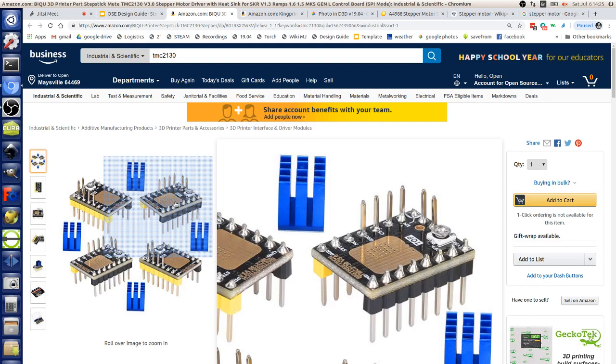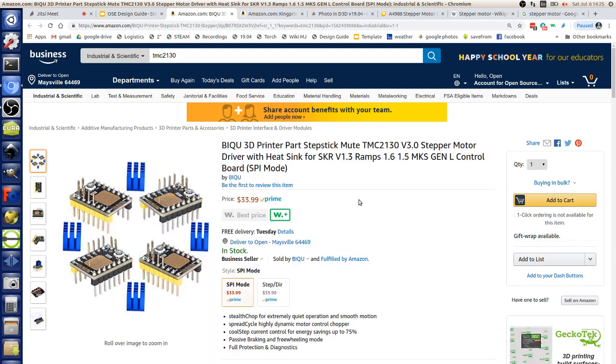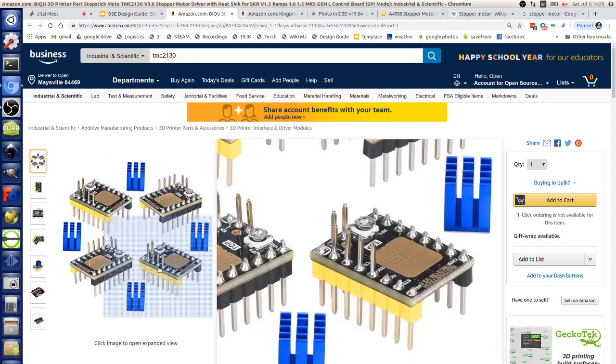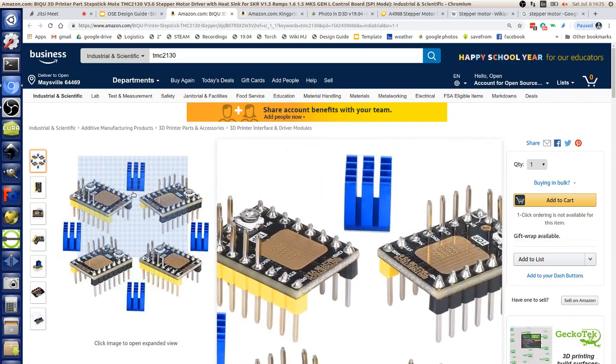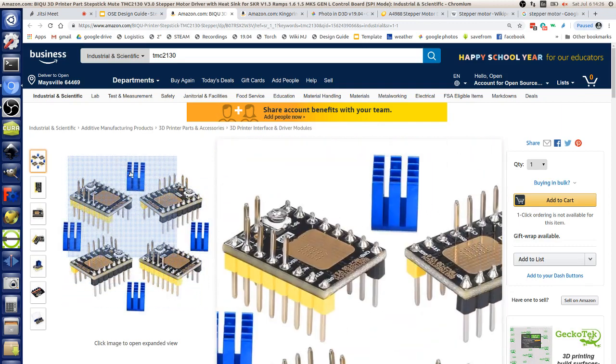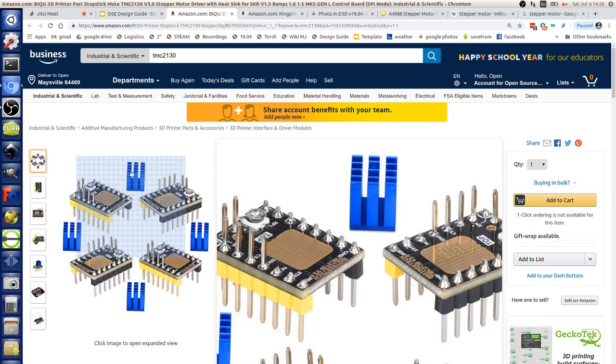So the usefulness here, one, is that you can have silent operation. Two, you can have the ability to use the stepper motor itself as the end stop sensor. Basically, when you hit the limit of where a given axis can go, you detect a higher current, and you're actually measuring that instead of using an end stop. So this allows you to use one less component in the 3D printer or universal access system. So that's very useful. It would be something good to develop on our side, to remove the need of using end stops, which take you a little bit to fabricate and put on.